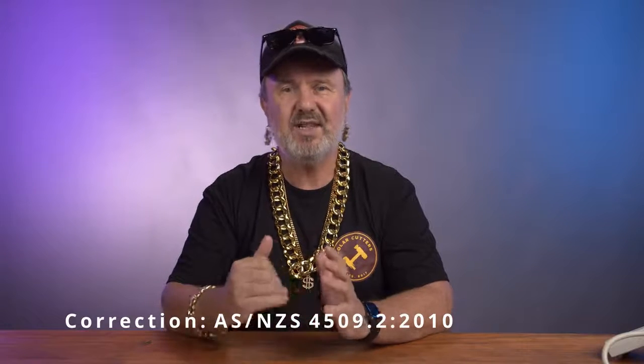How do we know what's the right size? Now, this is once again a budget question, but a reasonable approach, and this is following the principles of our design standard for standalone power systems, AS/NZS 5139, which says that you should consider coincidental loads. Now that means things that come on at the same time, and it can be with discussion with the customer, what's a reasonable expectation. So for instance, some appliances are almost always synchronized. If you have a water pressure pump and you use any appliance that uses water, like a dishwasher or a clothes washer, the chances are they'll both be on at the same time.